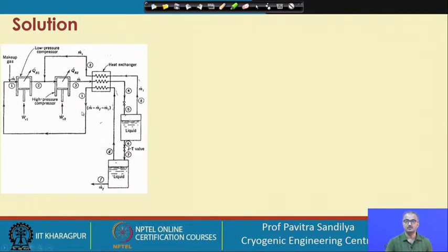So here, to recapitulate, this is a dual pressure system. Here we are using two compressors. The first compressor is taking from the initial pressure, which in our case has been given as about 1 bar, and it is going to the intermediate pressure, and that value has been given as near 5 megapascal, that is about 50 bar, and then we have been given the final pressure also. So we are given P1, P2 and P3, and then we are using some kind of 3-channel heat exchanger, and here we are using 2 reservoirs.